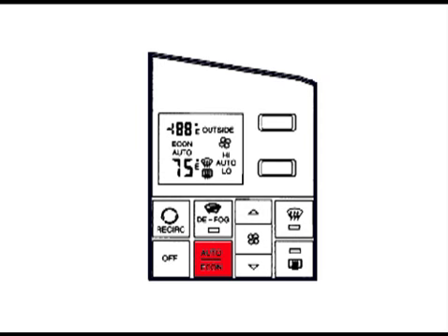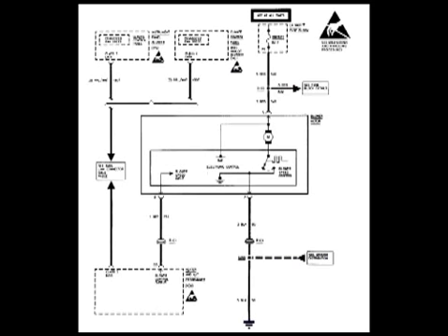Depressing the auto button will return the blower fan speed control to the initial automatic operation. Depressing either the top or bottom fan button will shift the blower fan speed control upward or downward through the additional automatic operations. The troubleshooting flowchart for the system starts by directing the user to look at the scan tool to verify the blower control is actually sending the proper command signal. A reading of 99 should be indicated when the high speed is selected.